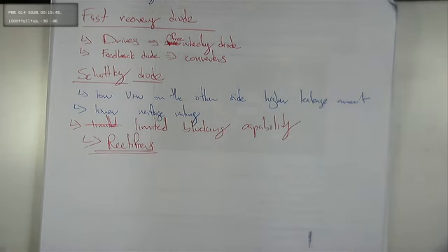So if a question is asked to you, how do you protect a diode, you will say to use a semiconductor fuse. In general for everything, either it's a diode, thyristor, GTO, IGBT, we use a semiconductor fuse.